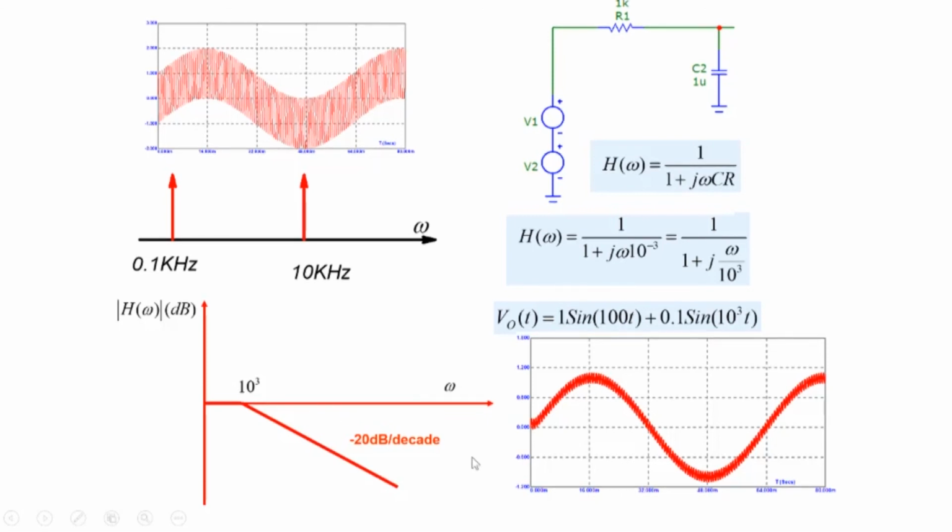For example, I can't shift the frequency from 10 to the power 3 to, let's say, 100 hertz, because then if it's 100 hertz 3 dB frequency, then my 100 hertz signal will also undergo an attenuation of about 3 dB. So it will also get attenuated, which is something that maybe I don't want. So you can play around a little bit with this number here. You could shift it here and thereby increase the attenuation of 10 kilohertz even further.